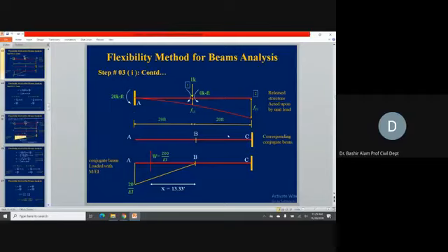Here, the conjugate beam you can see again, fixed to free and free to fix. Now here, this is the M over EI diagram, 20 divided by EI, and it is becoming a straight 1 degree because here we have 0 degree. So this is becoming 1 degree. We don't have any load here. The shear force will be having 0 degree and it is 1st degree.